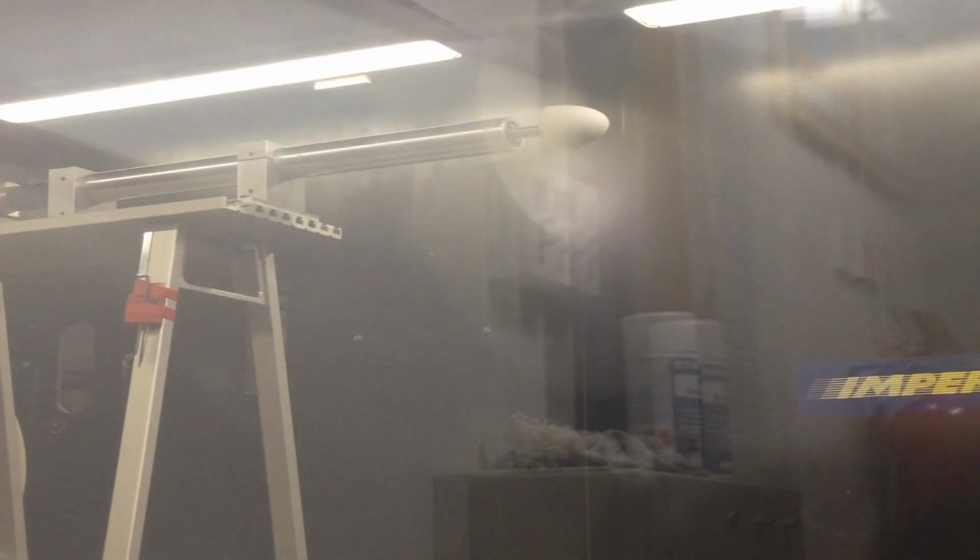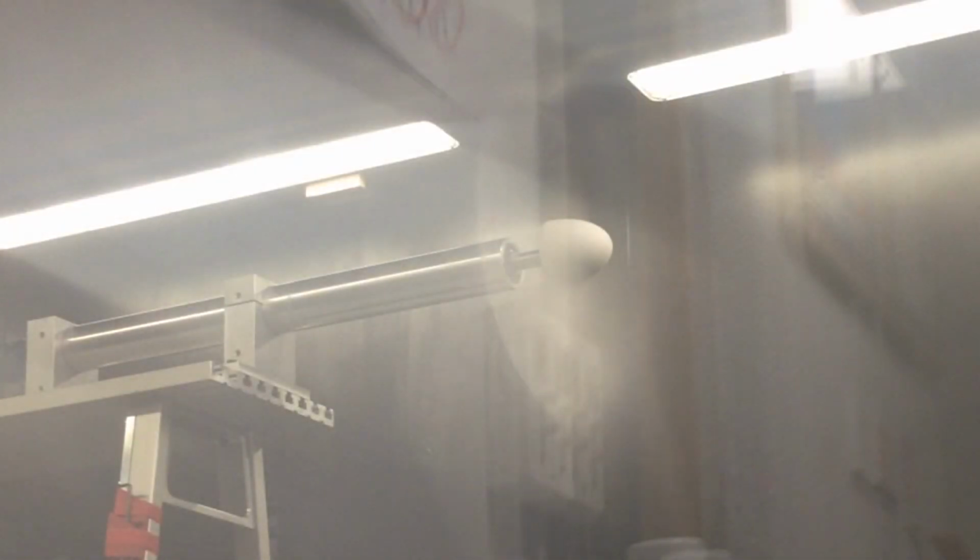Here's a few clips of how our blade performed. At 12 meters per second, Group 13's blade broke, but resonance was clearly visible at 10 meters per second. In future, it will be worthwhile designing for the avoidance of flutter, so their turbine would not be loaded at a natural resonant frequency, estimated using perhaps a lumped mass idealization.